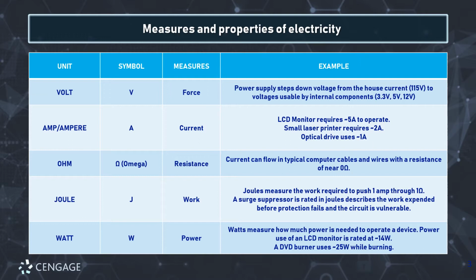You have a situation where you're kind of climbing up the hill, that tick, tick, tick, tick, and that's building up potential energy, right? So there comes a point where if you were to essentially stop cranking the cars up the hill, it would just kind of sit in place because it just kind of sits against the ratchet catch on the drive for the chain drive.